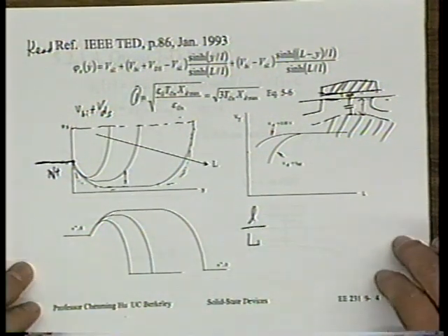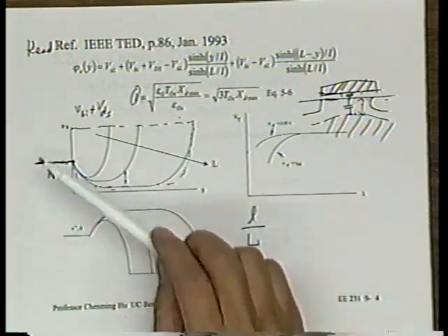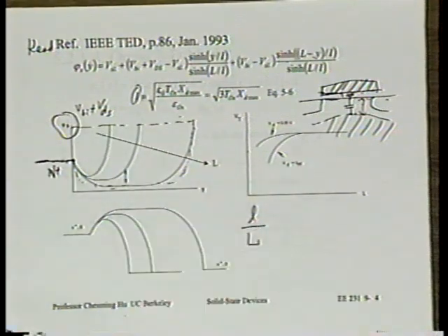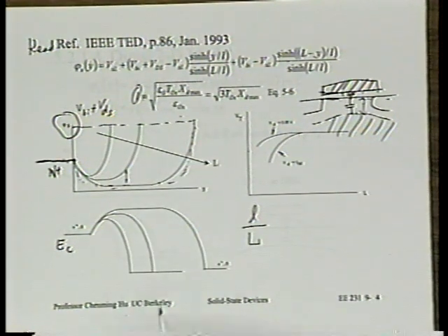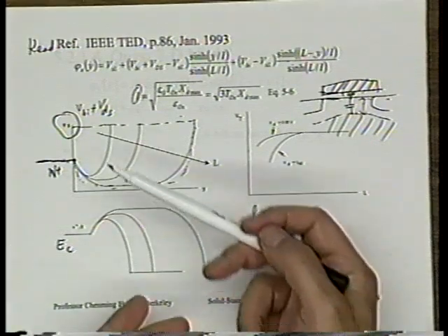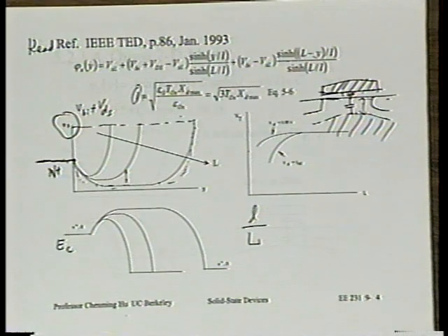All right, so let's finish this. Now, what do the top and bottom figures mean? The top figure is plotting the potential. The bottom figure is plotting the energy band diagram, called E sub C. Because we have drawn you several energy band diagrams, right? The energy diagram is just the potential's mirror image. That's all. Is that right?